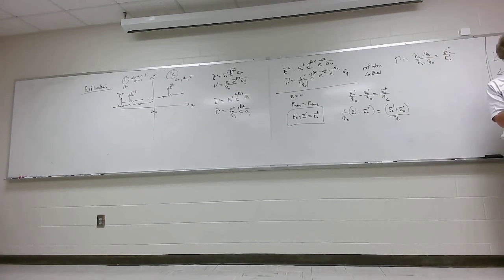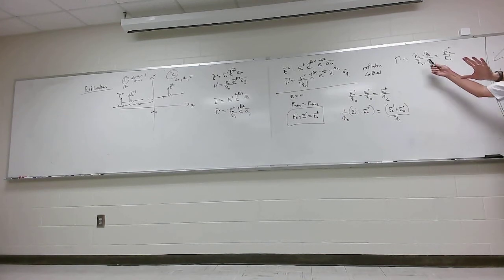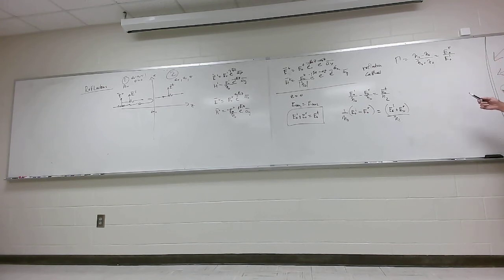Do you remember reflection coefficient from transmission lines? How many do? Well, I'm glad. Now here's the key with this. I'm putting it down. I didn't work through it because I'm just about out of time, but I want you to understand this. The way I always tell people to do this: if you're worried about reflection coefficient, the simple thing is go for the impedance you're going into, eta 2, subtract the impedance you came from, eta naught, and then divide by the sum. That will be the reflection coefficient whether you're in transmission lines or talking about propagating waves. You got me on that?